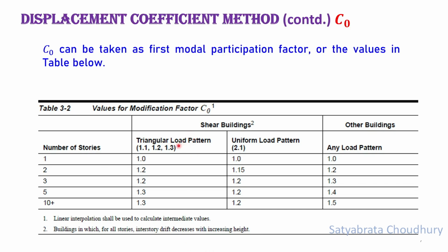Triangular load pattern nobody uses. For this, coefficients are given. Uniform load, you remember, we have used for pushover analysis. Other loads are not given, so it is not clear what you will take for other loads. Other than shear buildings, for any load pattern, you can take these values.